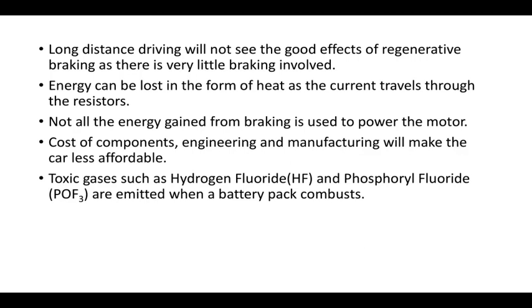And lastly, toxic gases such as hydrogen fluoride and phosphorus fluoride are emitted when a battery pack combusts. So in the case that the battery pack has been punctured and the safety features fail, the combustion of the battery pack will produce hydrogen fluoride and phosphorus fluoride, which are highly toxic and need special firefighting techniques to put out the fire.